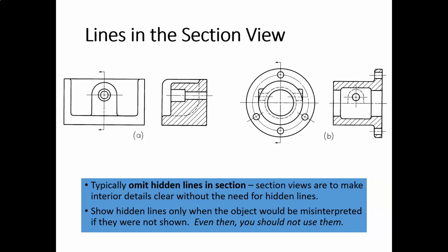Generally, it's for very, very special cases. In this case, the hidden line is intended to show this back surface right here. It's debatable whether this is necessary. The thing with hidden lines is you're not allowed to dimension to them. So you're showing this, but it's not clear what the dimensions of it are, so we can't dimension to it.